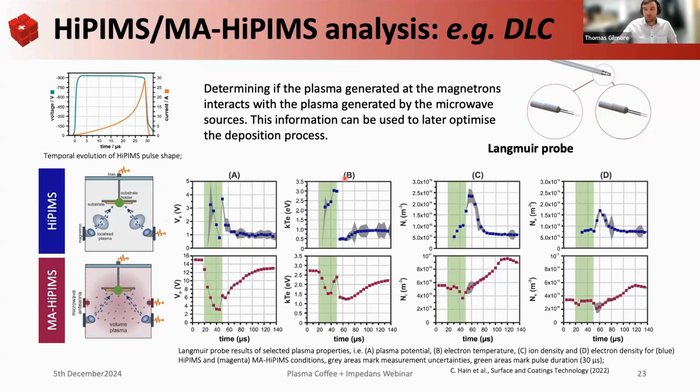How does duty cycle influence the rate and quality of deposited films? With a higher duty cycle you have more on time, so you will have higher deposition rates in essence. As for the quality, it depends on many more variables than just the duty cycle.